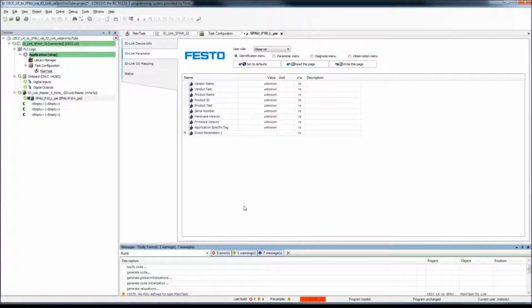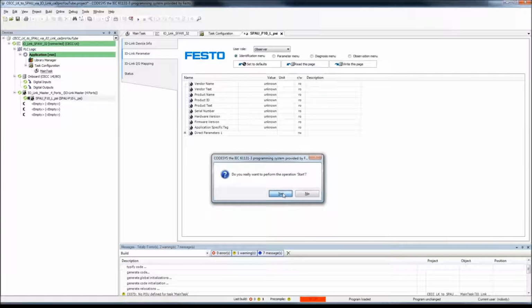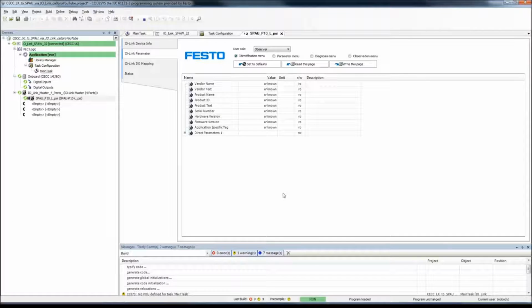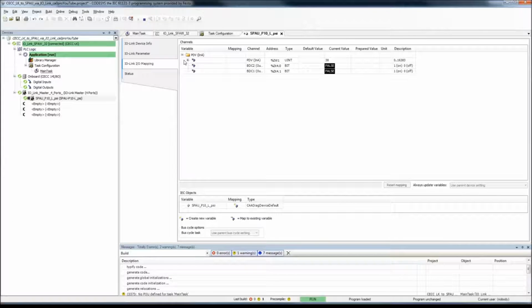And if all you're doing is wanting to get the process data variable, then you're done. You've got the IO-link mapping, you've got the process data variable, and right now my pressure on my LED display is reading 2.3. But look, it says 261. And what are these 0 to 16,383? Well, those are engineering units because they don't scale it for you, unfortunately.